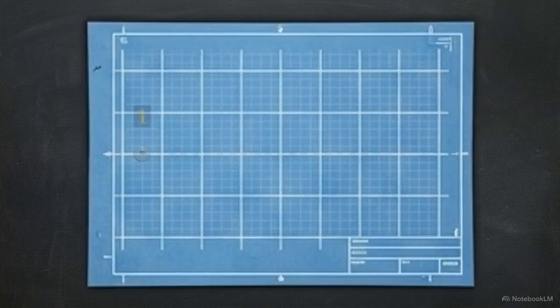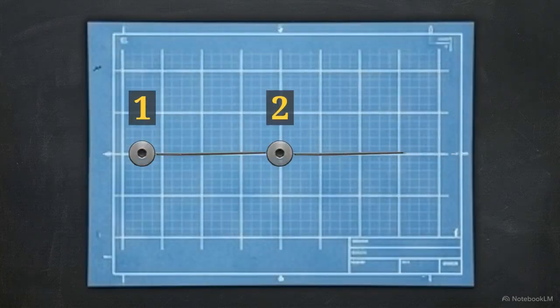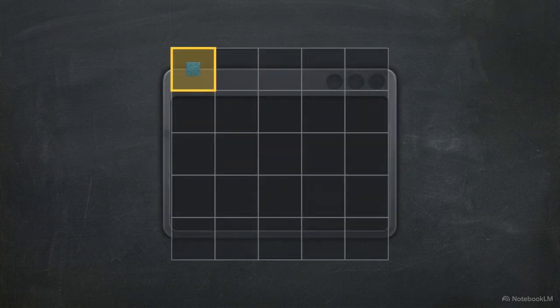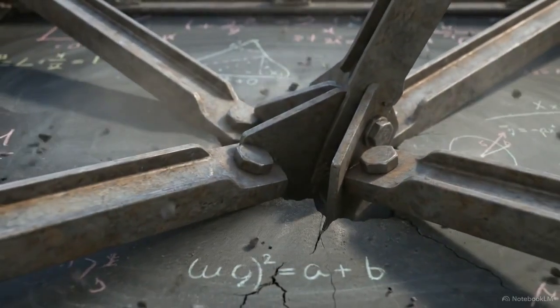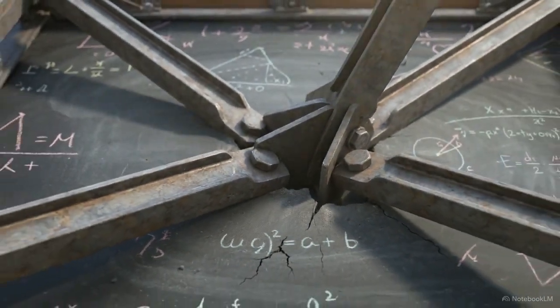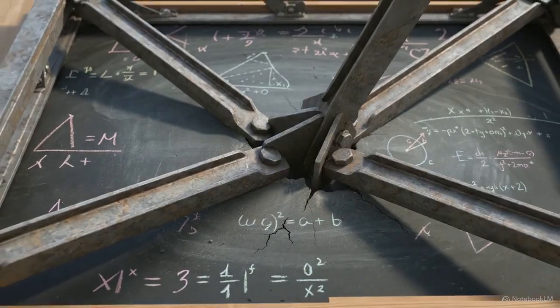In a one-dimensional finite element model, the math is straightforward. The bars connect in a single straight sequence, making it easy to assemble the stiffness matrix because every node follows the one before it. A two-dimensional truss structure is different. Its elements share multiple nodes and connect in a non-linear fashion at varying angles.